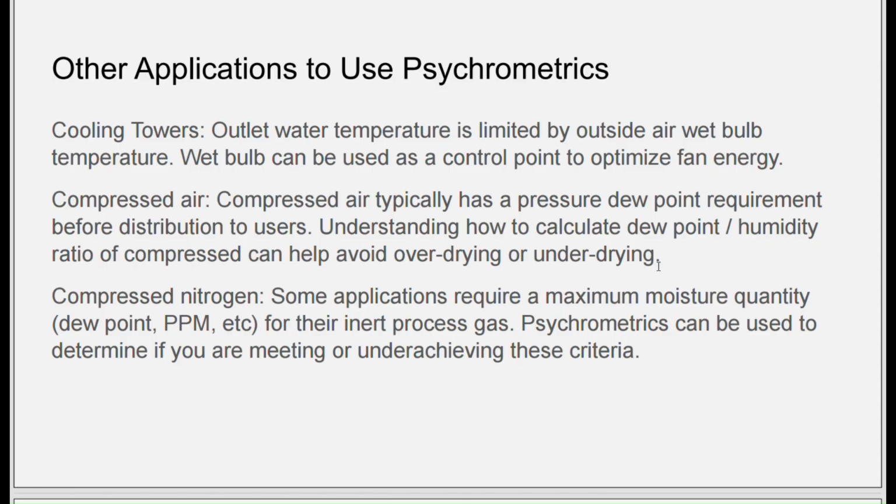Compressed air is not something you often think about using psychrometrics for, but dew point and moisture content of compressed air is important. And if you're going to do any type of detailed analysis on that, you end up doing psychrometric calculations to look at dew point and humidity ratio of that air.